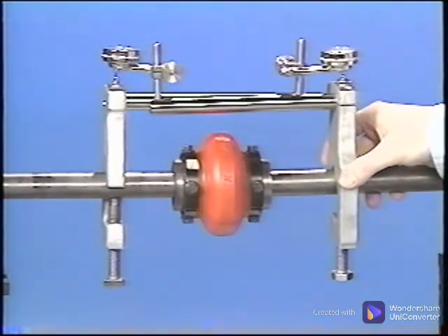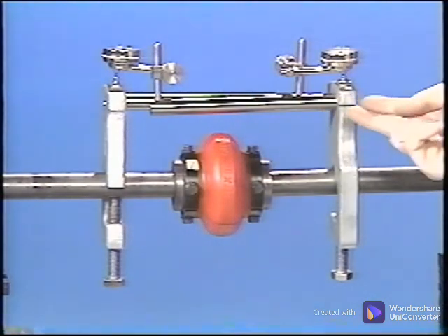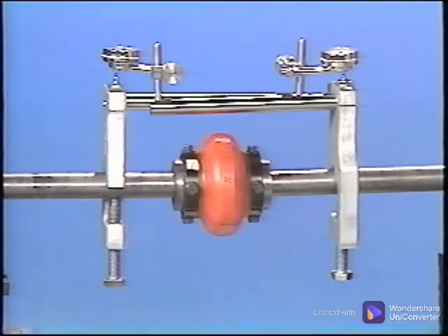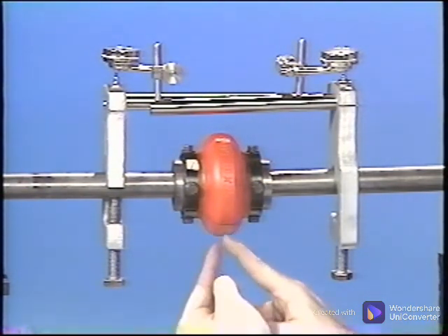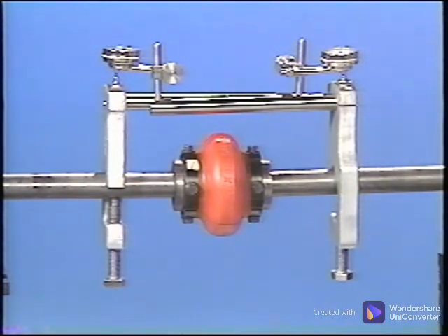The reverse dial indicator method is used when both shafts can be rotated together. A dial indicator is mounted on each shaft, and the dial is actually measuring across the coupling to record the relative movement of the opposite shaft. These measurements are then mathematically or graphically projected to the machinery feet, where corrections are then calculated for adjustments and shimming the feet. This method can be used for longer spans than the face rim method, and because the shafts turn together, it is independent of coupling runout.